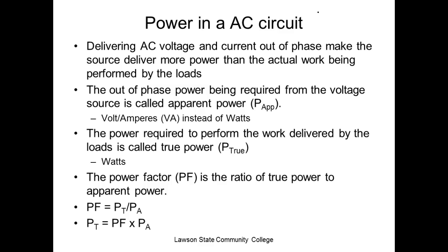You can buy capacitors, they call them power factor capacitors, that you can buy for your house if you get them online, but that's kind of like the people who say you can increase the efficiency of your car by 150% if you install this little gadget on there. The problem is if you overcorrect, it's just as bad as undercorrecting, right? You understand? The power factor for residential customers is compensated for by Alabama Power. It's just big companies that have to worry about the power factor. They had one guy at U.S. Steel, Ed Vining, and that was his job, to monitor the power bill and the power factor at the company.